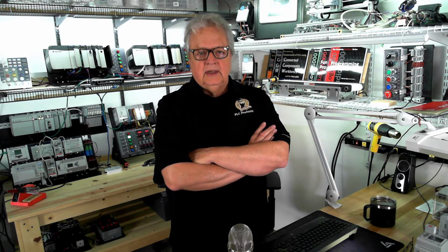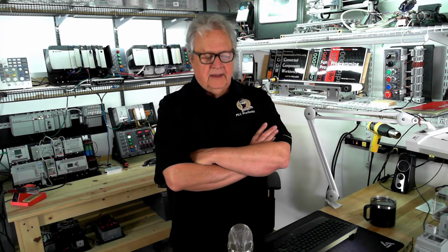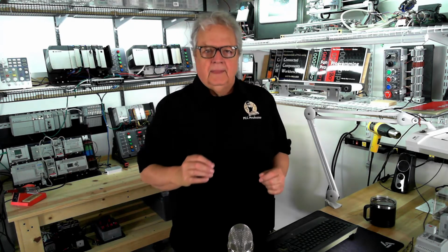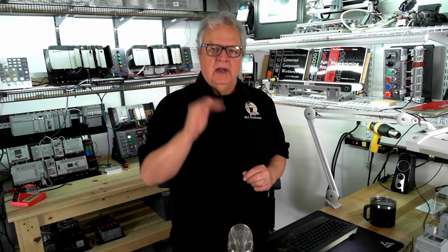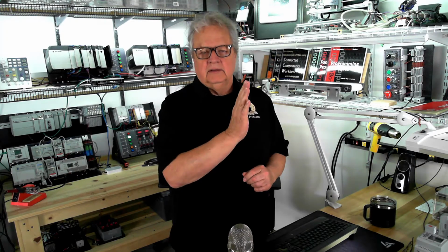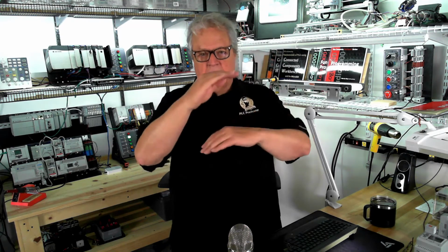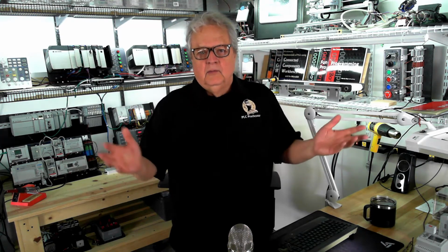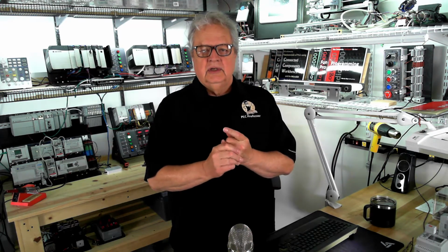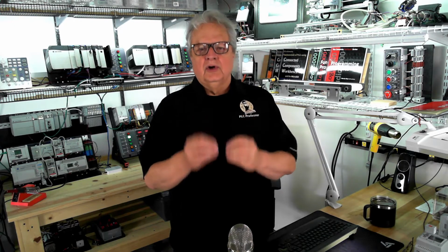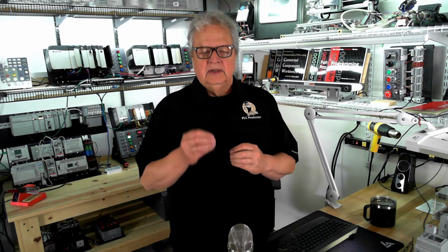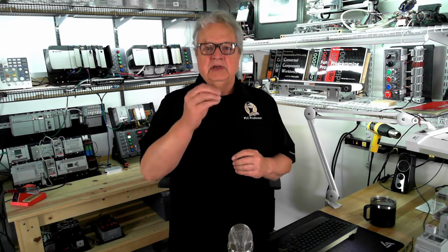rung it is scan dependent, meaning that when you scan a rung, it's top down and then it's left to right. If within that rung you switch some of the branches around, you won't get the same results. So these rungs internally are scan dependent. It's not scan dependent logic between rungs.